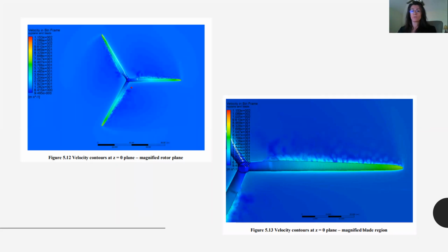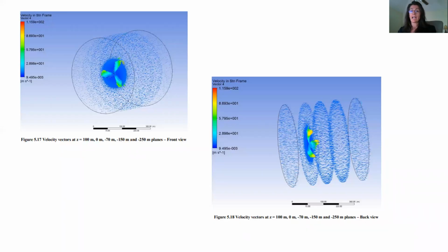Turbulent flow is examined using velocity, pressure, and stress fields. The aerodynamic torque and power produced by the wind turbine was calculated. Outer diameter of the computational fluid domain was selected 3 times larger than the diameter of the rotor to make sure the flow could be seen away from the rotor region. The total length is 350 meters long with a length blade region of about 100 meters long.